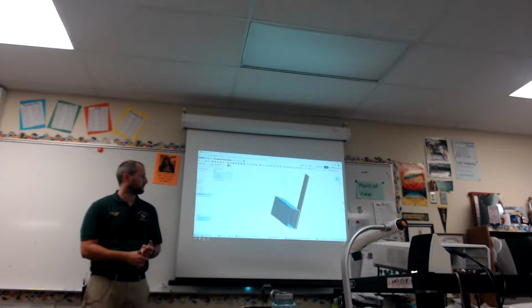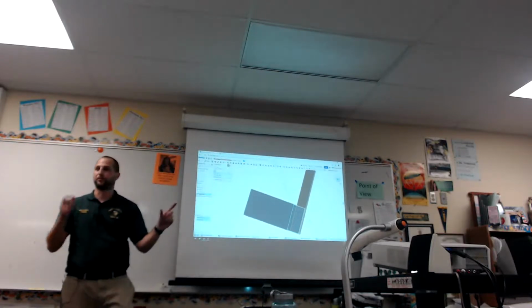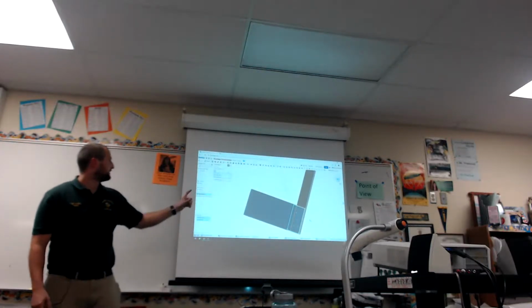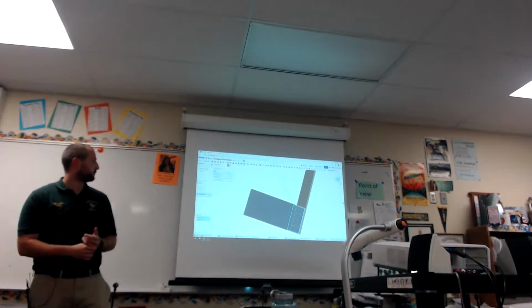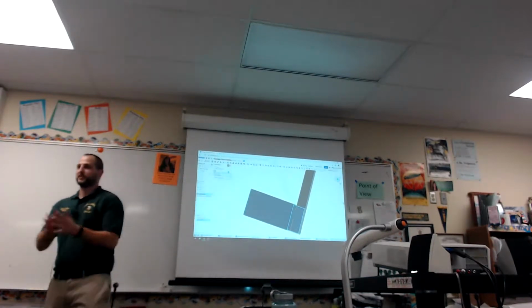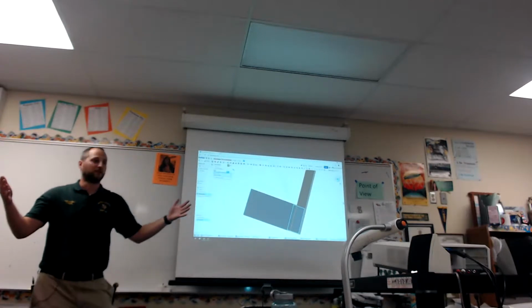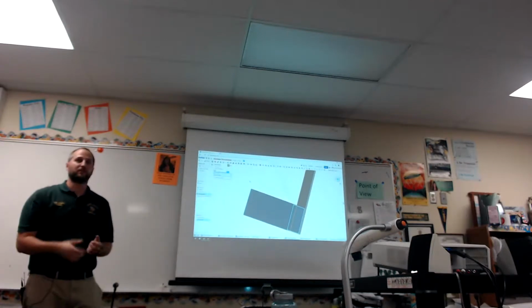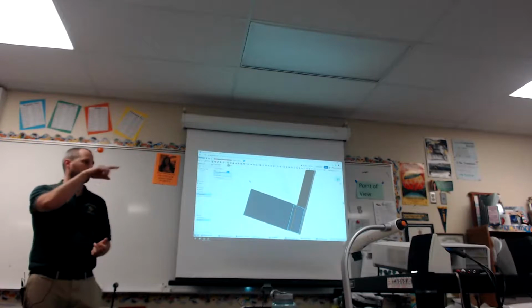And if Tony goes and looks at the inside of that tube, and we're cutting through both parts, he selected both of them. If he deselects the aluminum 2x1 in the parts to cut list, it doesn't matter how big we make this hole. We can tell it it's 12 inches, 18 inches, 2 inches. It's only going to cut through the selected parts. So it'll skip parts that you don't select.